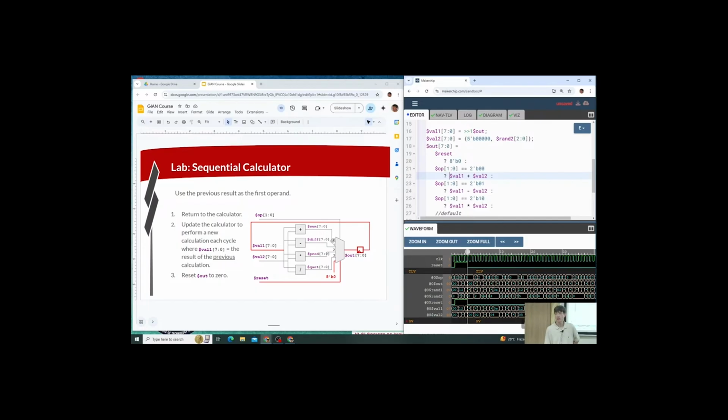Yeah, so logic synthesis, you know, it's possible that the library that logic synthesis is working with has perhaps a 4-to-1 mux, right? Generally, it's going to be working with lower level things. But it's up to logic synthesis to take the logic as we've described it and map that to the physical cells that it has available. So this doesn't mean there's a 5-to-1 mux cell. It just means that's the logic function that we want, and then it's up to logic synthesis to make that happen.